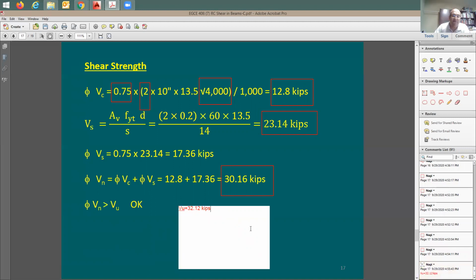All right, how can I figure out the reinforcement needed? Well, you say at least concrete strength and the steel strength is going to be equal to the demand. Don't you agree? Which means phi, the phi factor, times Vc plus Vs is going to be equal to what? Like numerical value. Would it be the 32.3? Yeah, very good.